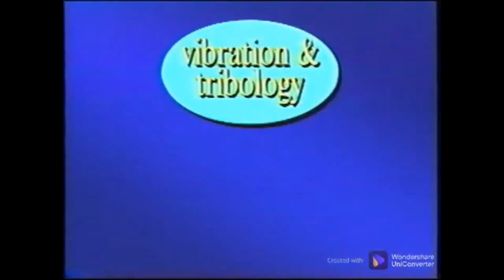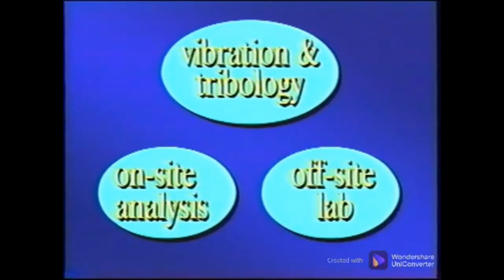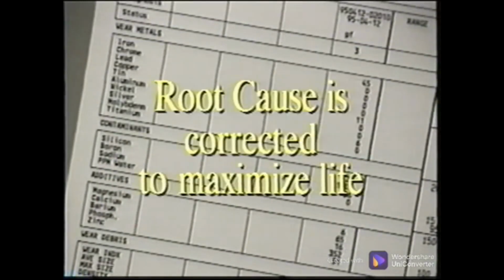To achieve this RBM approach, the vibration analyst also has a working knowledge of tribology, with on-site capabilities as well as an electronic link to an off-site lab for results and a direct link to a computer maintenance management system for immediate responsiveness. Oil analysis in a reliability-based maintenance environment has the greatest potential for savings because the root cause of oil contamination, degradation, and machine wear is searched for and corrected to achieve maximum life for the machine and the lube.